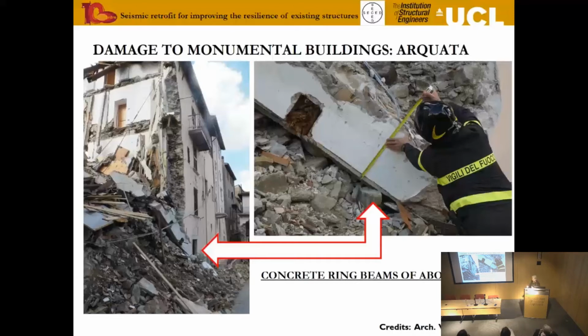But interestingly, by the time they did this, it had become fashionable to have timber roofs, and it was said that no, timber roof is fine, as if they are properly designed and everything. You can see that the structure framing into that ring beam under the roof was made of timber, which of course could only shear off because of the stiffness of the ring beam.